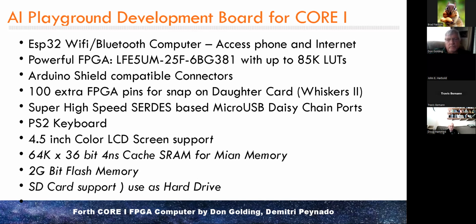So that's one thing to take into consideration before you commit to a particular design and then realize that, wait a minute, either you want to use these 5 volt Arduino shields, or you want to be compatible with everything else in the world that runs 3.3 volt or 1.8 volt. Yeah, so my thinking is I would rather make it a requirement that you have to buy the 3.3 volt version.